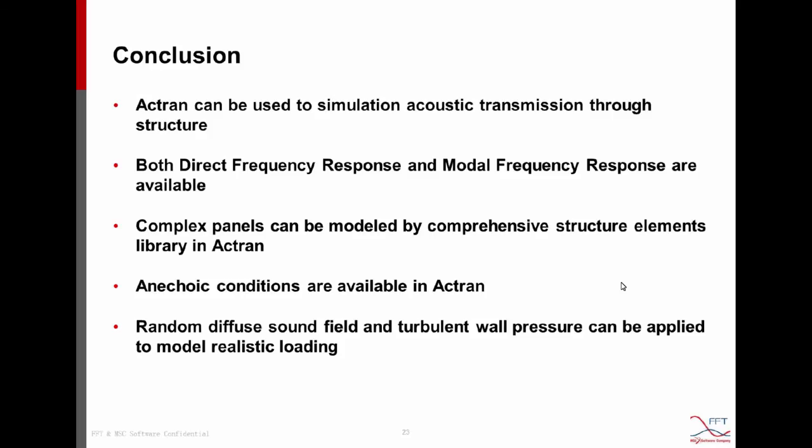Now to conclude, we have seen that Actran can be used to simulate acoustic transmission, or in other words, acoustic insulation through structures. So both direct frequency response and modal frequency response are available for different purposes. Modal frequency response is suitable for lightly damped structures, and direct frequency response is more suitable for highly damped, complex damping and porous material.